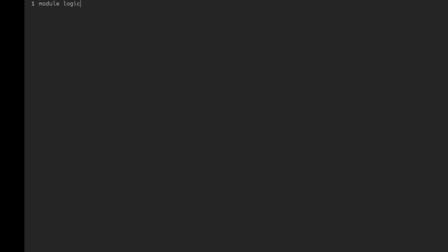Let's name our module logic gate. Let me first save this file. Okay, so we have two inputs A and B, and within the same module we will be generating all three outputs, that is output AND, output OR and output NOT. For simulation purposes and also for FPGA development purposes, we will be following the data flow methodology, or the data flow process of writing the Verilog code, that is using assign statements.